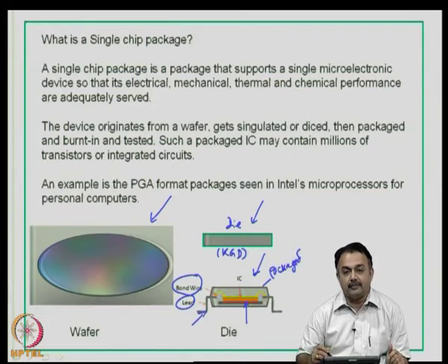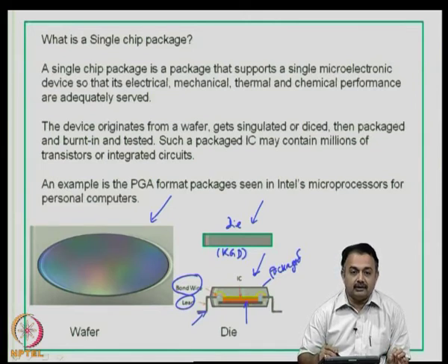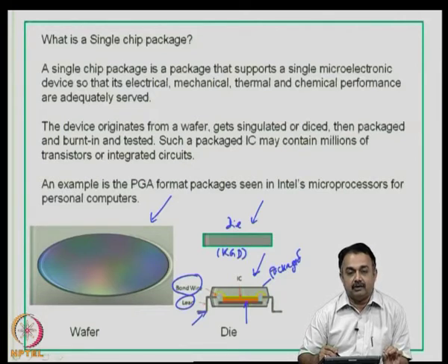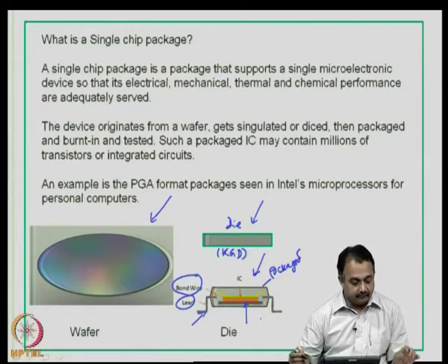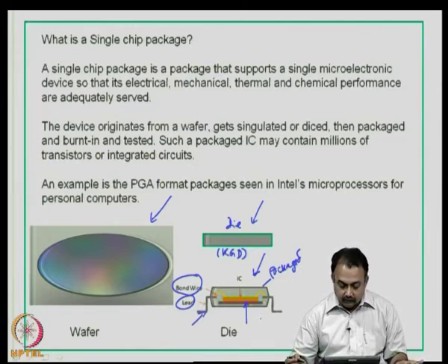or encapsulated. So, you have to choose a suitable encapsulant and then mold the material, so that you get a well defined thickness of the plastic material, and as per quality you can check the thickness, the length of the lead frame and so on, and then send it into the market. So, wafer to single die to a packaged die.